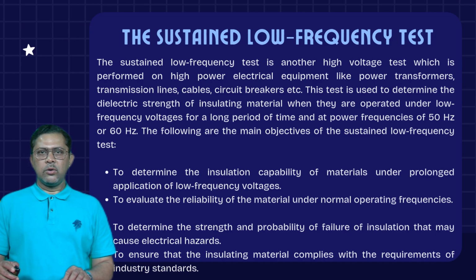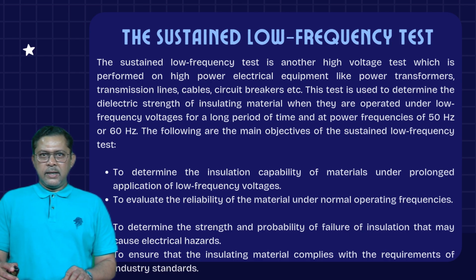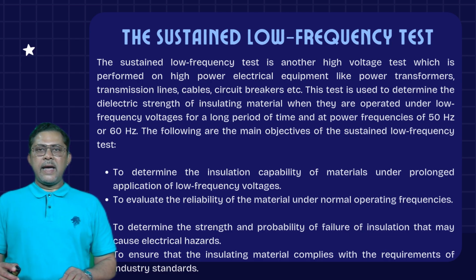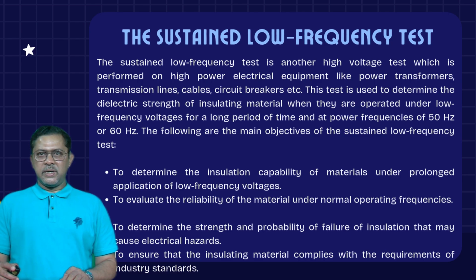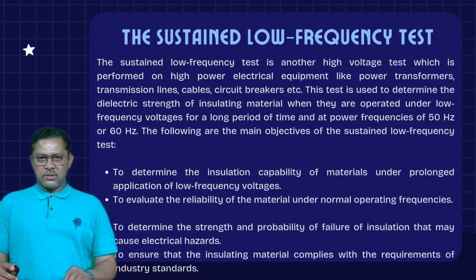The sustained low frequency test is another high voltage test which is performed on high power electrical equipment like power transformers, transmission lines, cables, circuit breakers, etc. This test is used to determine the dielectric strength of insulating material when they are operated under low frequency voltages for a long period of time and at power frequencies of 50 or 60 Hz.